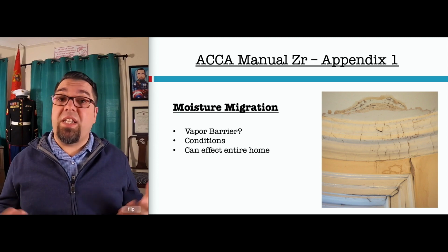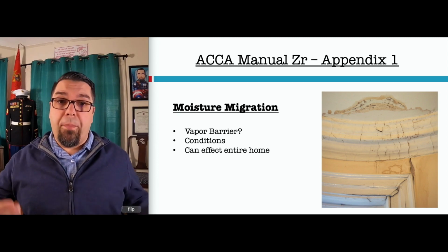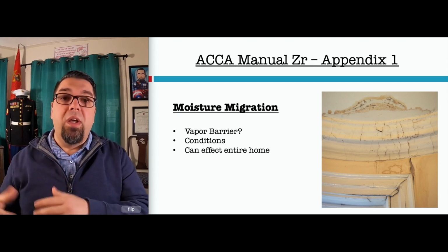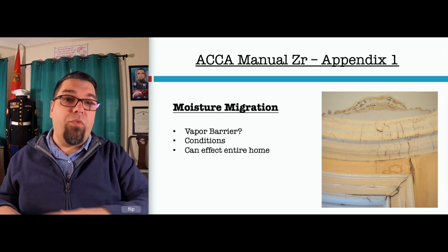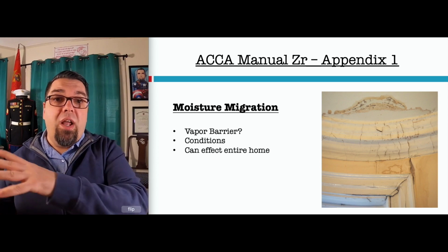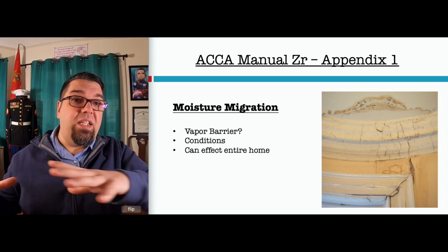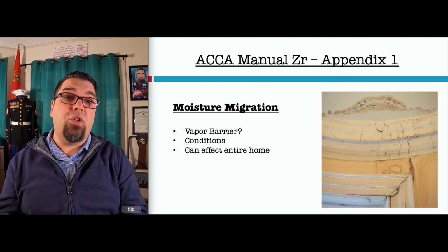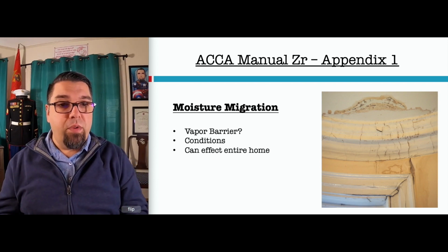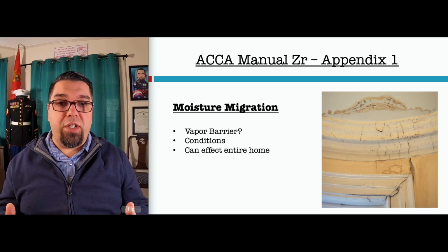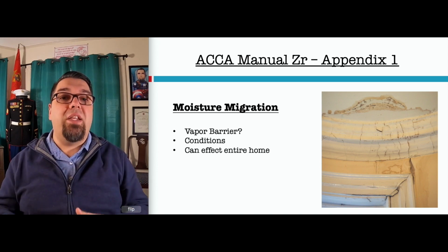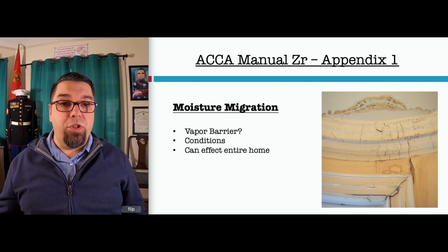So if you have, let's say, ductless all on the first floor, it probably could be controlled in that one room because you have a ductless wall mount in that one room. If you have a ducted system on the whole first floor, the air and moisture is going to mix in the entire first floor to get back to those returns in order to come back to the coil to remove that moisture. We only change sensible temperature in each room with airflow. Moisture is removed at the coil. It's going to affect the entire home if you can't control the moisture in a house.